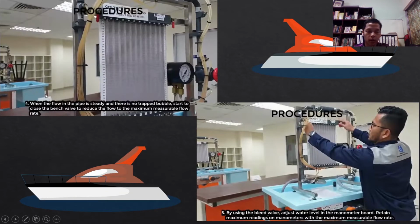Number 4, when the flow in the pipe is steady and there is no trapped bubble, start to close the bench valve to reduce the flow to the maximum measurable flow rate. So when the flow in the pipe is steady, there is no trapped bubble, and then we start to close the bench valve to reduce the flow to the maximum measurable flow rate.